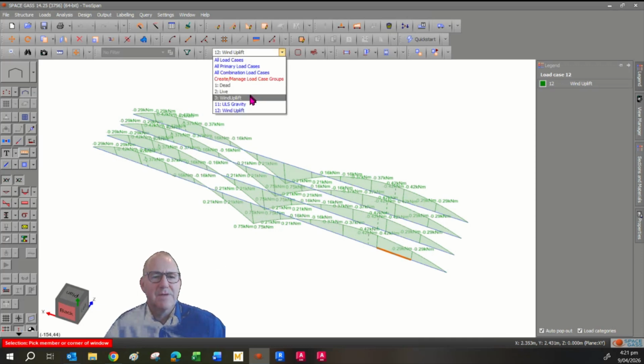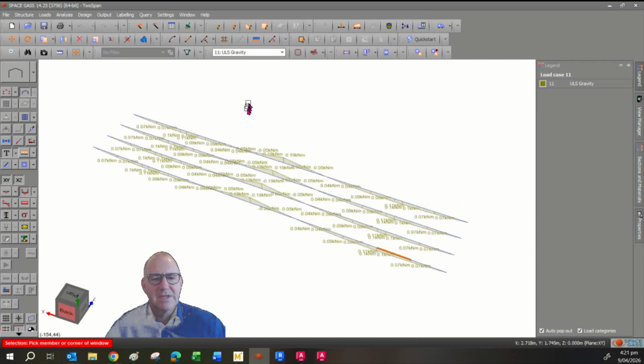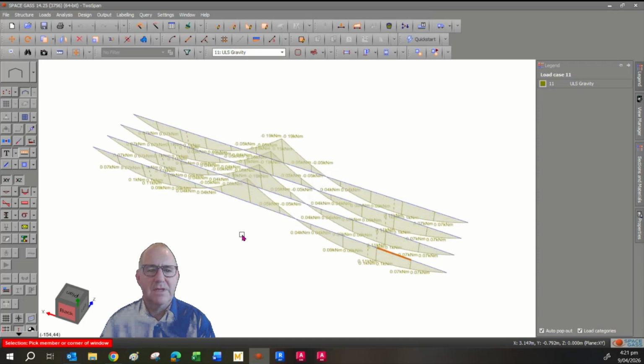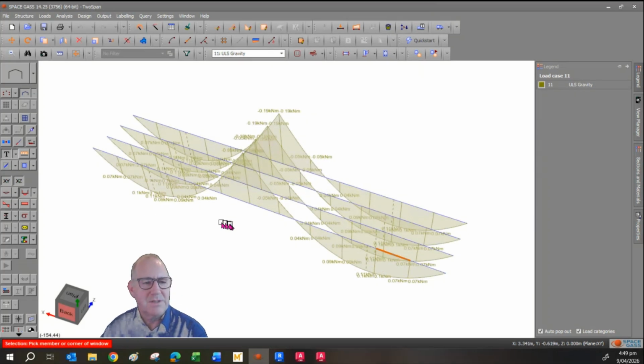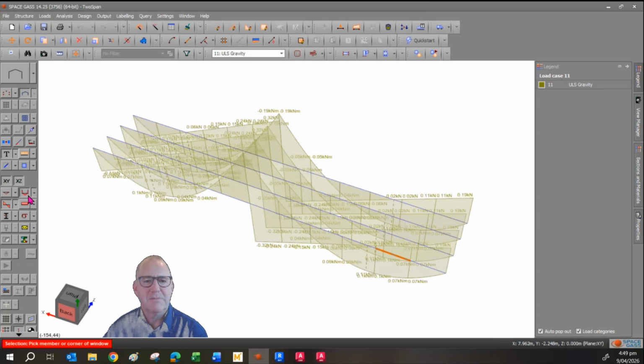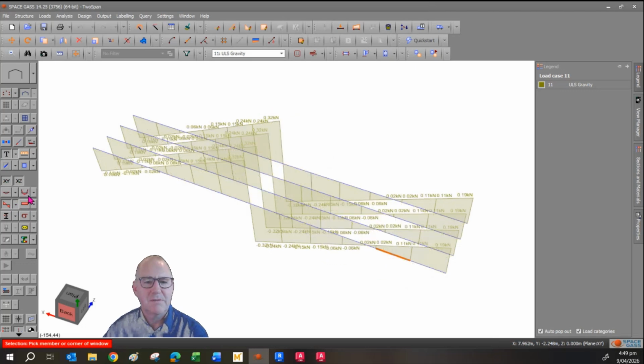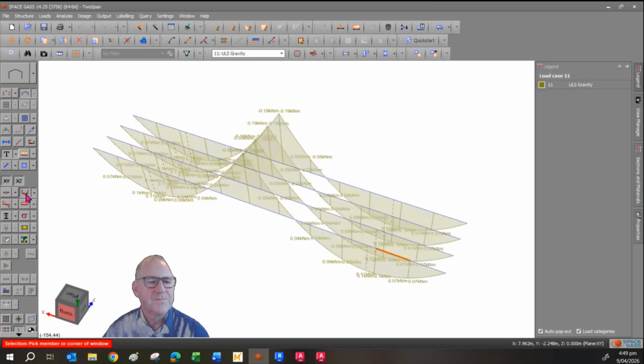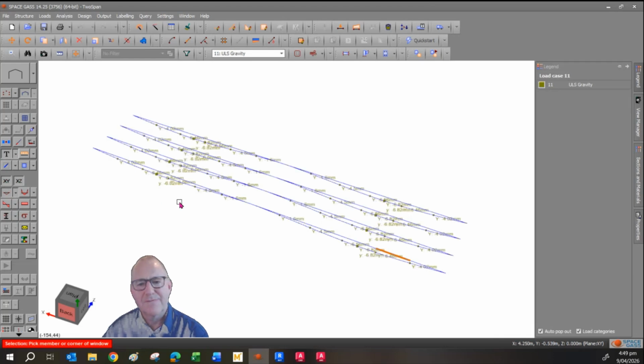That's for wind uplift. How about gravity loads? Similarly, it's that profile that you would get for vertical loading on the way down. If we want to look at the shear, click on the shear diagram, but switch off the bending moment, and they're pretty much as you suspect. So take them both off, and if we want to look at the deflection, click on the deflection button.